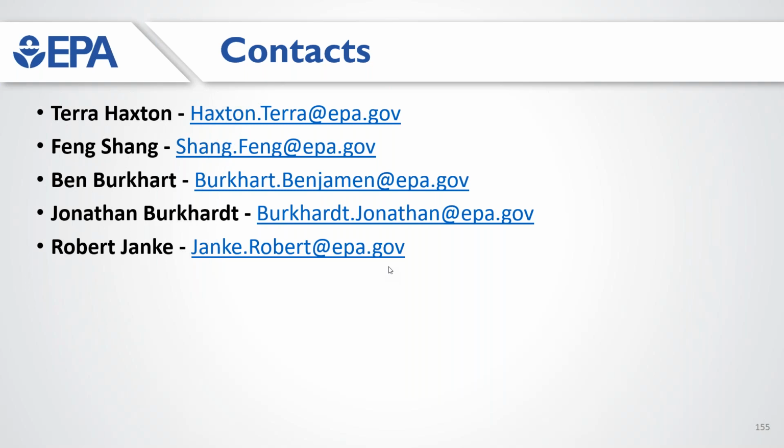All right. And here's another one probably for you, Feng, as well, or any of us: can EPANET analyze fire flow? Yeah, it can, because you can just assign huge demand to nodes and see how pressure differs.